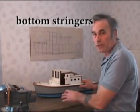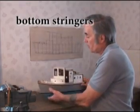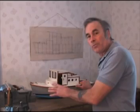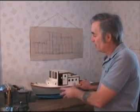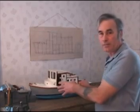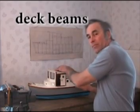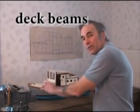And they support the bottom stringers. This boat uses bottom stringers, three on a side. The bottom plywood fastens to the stringers, and the stringers themselves fasten to the floor timbers and the bulkhead floor framing. And that's what makes up what we call the skeleton of the boat. The keel and the frames and the bulkheads make the skeleton. We also have cabin framing pieces to support the sides of the cabin. We have cabin deck beams, or cabin top beams, and I have a main deck beam going across here. Deck beams are frames that support the deck.